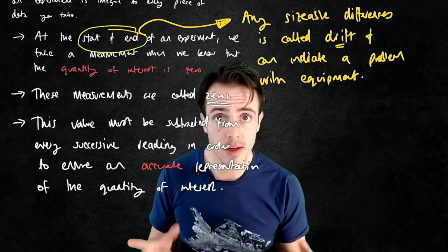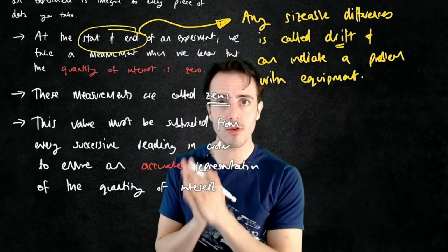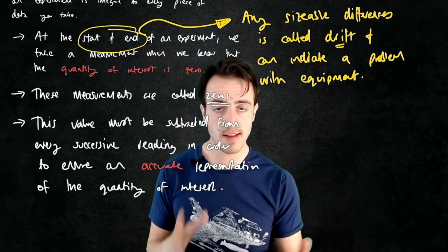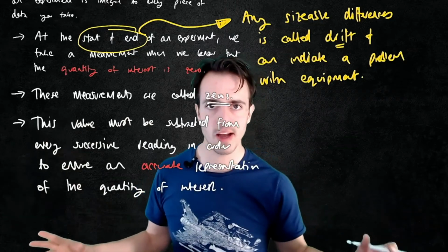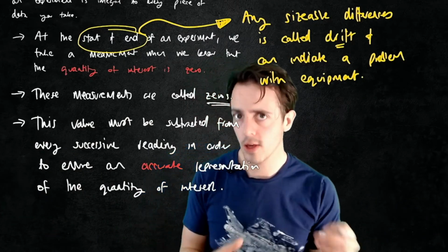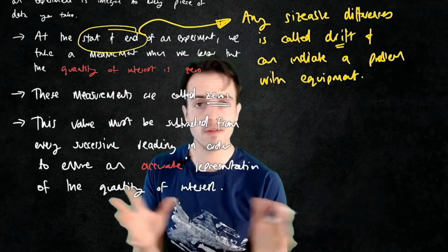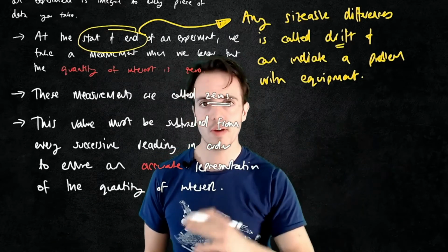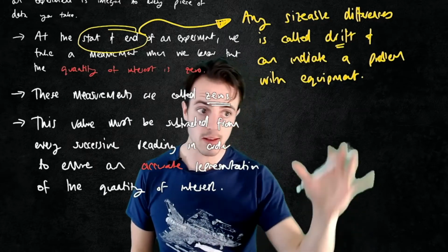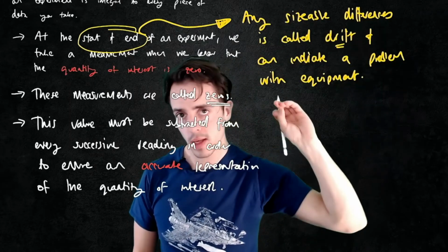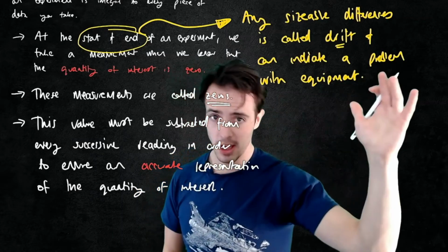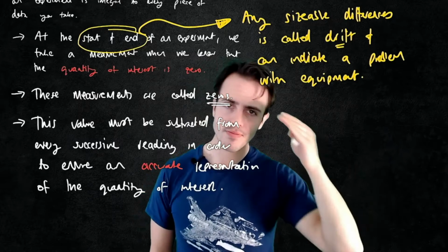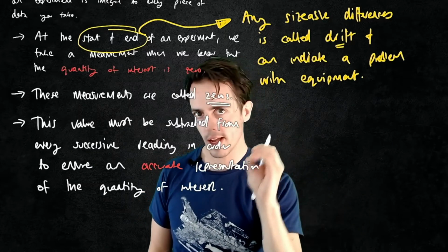Things heat up. Transducers are inherently electrical devices. With current going through them during an experiment, they heat up, and everything else in your experimental setup is also probably producing heat. Or maybe it's producing cooling, convective cooling by blowing air over your equipment. In general, we know that all electrical devices change their resistance dependent upon heat. So you will see this occurring in a small amount, but any really large changes, bigger than 1 or 2%, are something you want to observe and take account of.